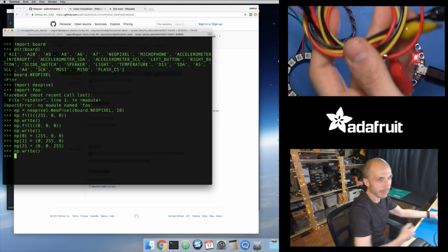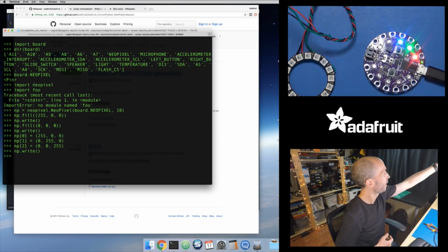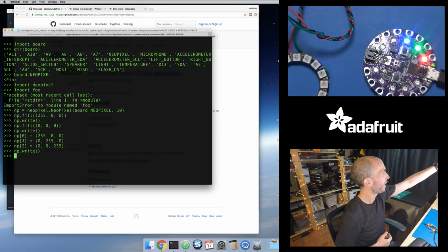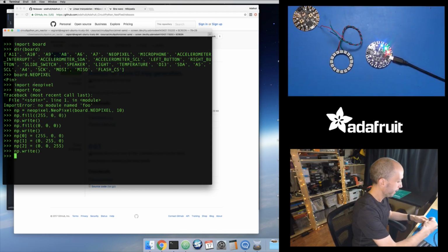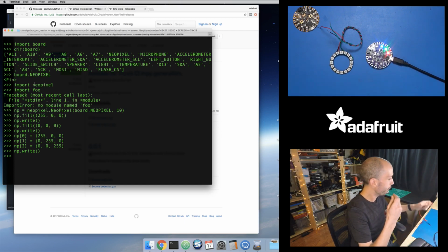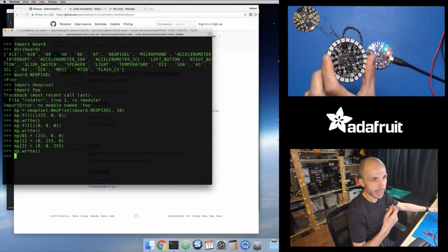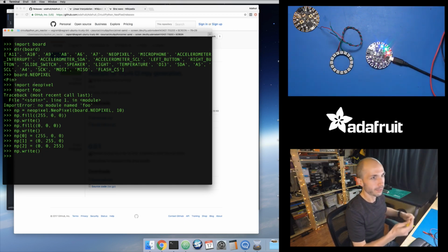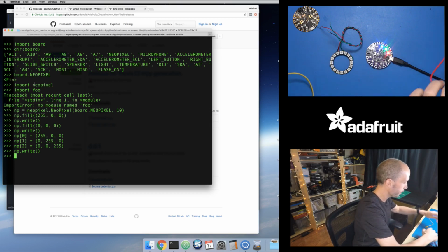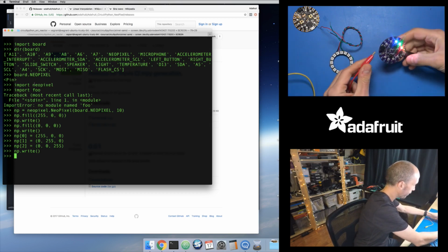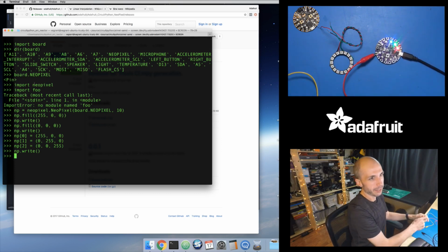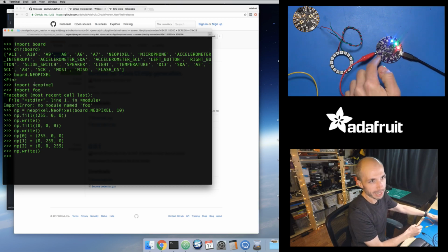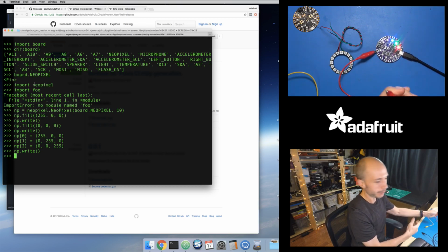So to make this easy, I'm just going to use alligator clips, or these little alligator wires. These are super handy. Let's zoom out a bit so we get a little bit more of the workspace visible. This is very easy to wire up. I'm going to wire it up exactly how I have the non-CircuitPython version wired. So let's do the red wire to the VBAT input. That's the battery output on here. That's the nice thing about any of the Circuit Playground boards. They have these nice wide holes, which are perfect for alligator clips, so I don't even need to solder things onto here.